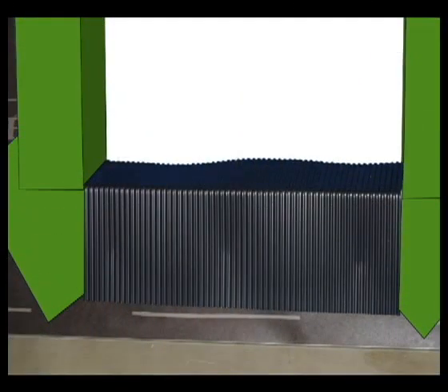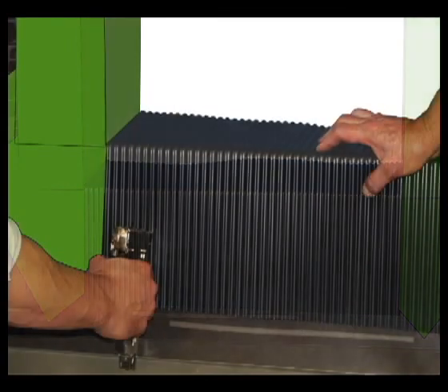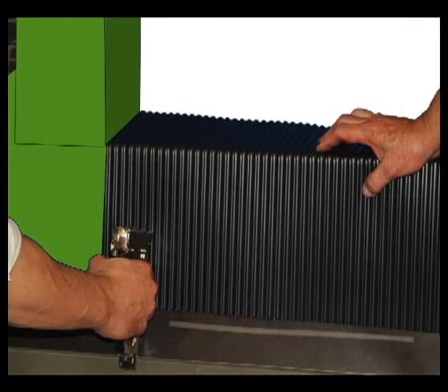Install the window drainage plane into the bottom of the window rough opening. Fasten the window drainage plane on the face of the wall with staples. Do not staple the top of the window drainage plane.